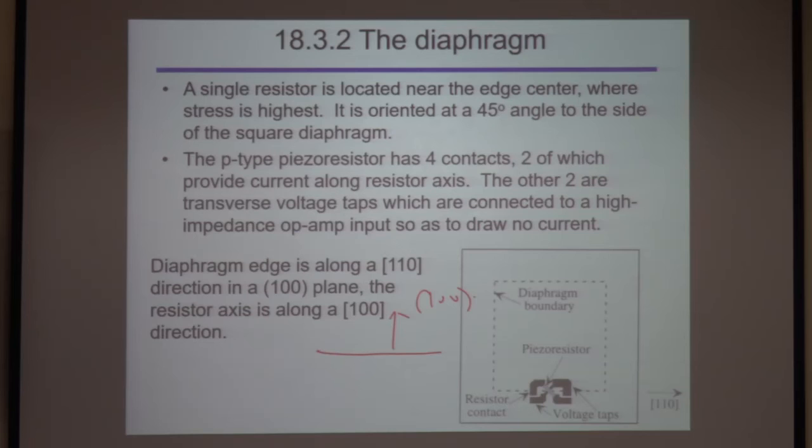The 111 surface has the maximum number of atoms compared to 110 and 100. So for anisotropic etching, the etchant attacks the 100 and 110 surfaces, and the etching speed on 111 is the slowest, while 100 is the quickest.